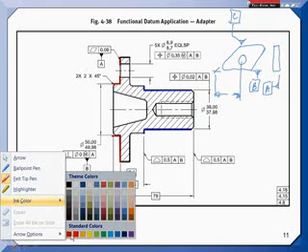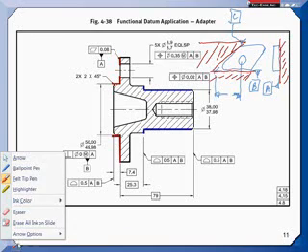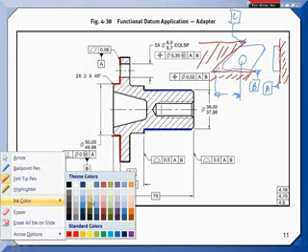I'll change colors here. Because what I've shown you so far are the datum features. The datums themselves will be simulated by a nice plate here. And we'll have a simulator here. And we'll have a simulator at the basic angle here. I'll exaggerate it a little bit. Okay, but I'll put it at the basic angle. And then I slide my part into this setup. Now, where are the datums? I haven't shown you them yet. Let me go to some other color.